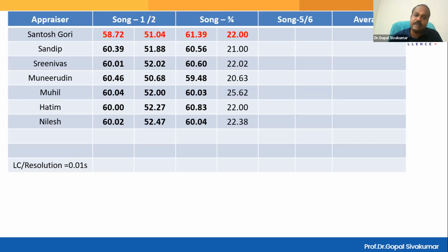And third reason, 10 parts. Fourth guideline, you should cover the entire range. Cover the entire range with a 50-50 ratio: 50% of the parts are closer to the target value and 50% of them closer to the specification. So now you can boldly say 50% are good and 50% are bad. Once again, 50-50, sir? Yeah, 50-50. General practice is 50-50. So with all these guidelines, you can now proceed.